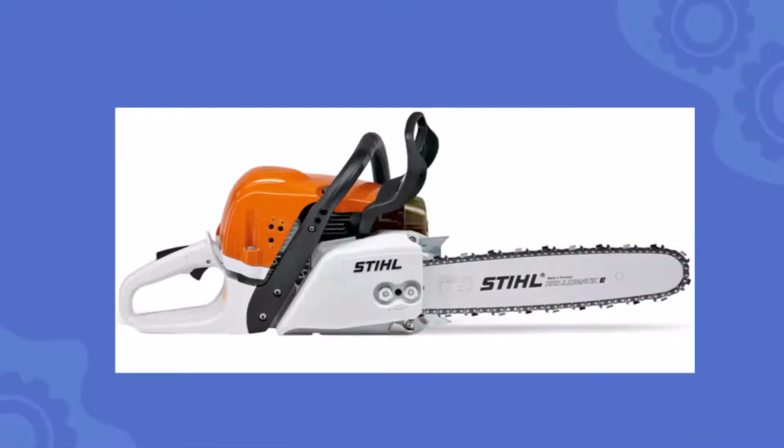A Stihl 311Y petrol chainsaw features a two-stroke engine, a carburetor, an oil pump, and an electric ignition system. The chainsaw takes in the fuel-oil mixture and air. The carburetor mixes air and fuel, then sends the mixture into the piston inlet. The piston head raises, compressing the mixture and increasing pressure. The spark plug ignites, and the engine is started, which moves the chain for maximum sawing power.